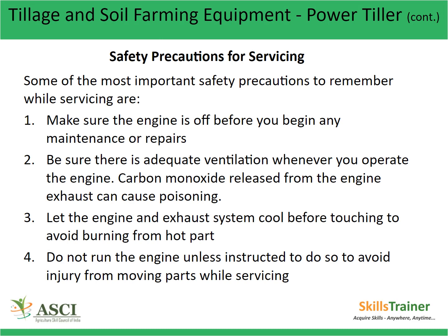Safety precautions for servicing. Some of the most important safety precautions to remember while servicing are: make sure the engine is off before you begin any maintenance or repairs. Be sure there is adequate ventilation whenever you operate the engine. Carbon monoxide released from the engine exhaust can cause poisoning. Let the engine and exhaust system cool before touching to avoid burning from hot parts. Do not run the engine unless instructed to do so to avoid injury from moving parts while servicing.